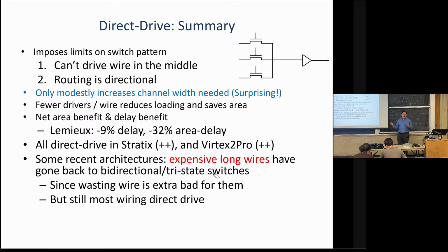Okay, so long wires are getting essentially more expensive. I'm going to show you a couple pictures that indicate why. To go a long distance without routing switches, you have to go high in the metal stack because that's where you can make wires that are quite wide and they're manufactured to be quite thick. So the combination of those two things is their resistance is pretty good. And that's what allows them to go a significant distance quite quickly without extra routing buffers. But you can't build very many of them because the reason they're fast is because they're not scaled as aggressively.